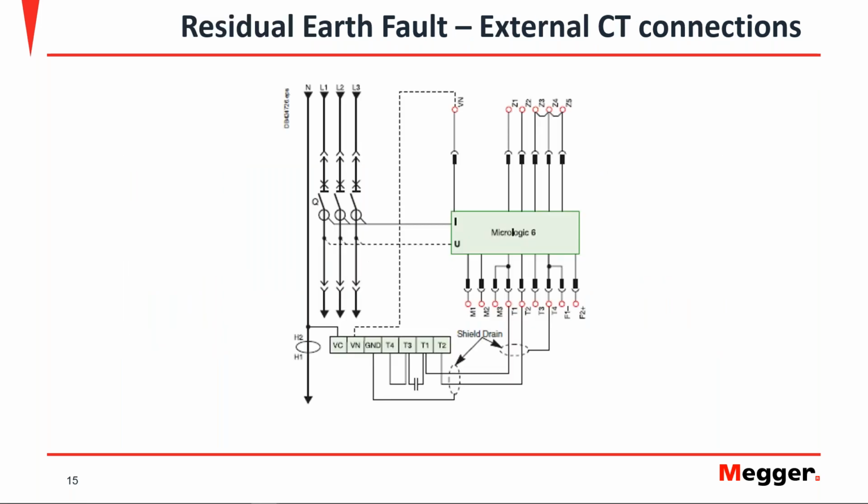Okay, so 3-pole and an external neutral CT. Now, when we perform these measurements, understanding the CT polarity and the proper external neutral CT, in case we have one, like in the example I'm showing you now in the slide. This diagram, I took it directly from a manufacturer manual. I don't know if you can see the Micrologic 6 label in that box in the middle. That section from which I took this diagram explains the external neutral CT connections, right?